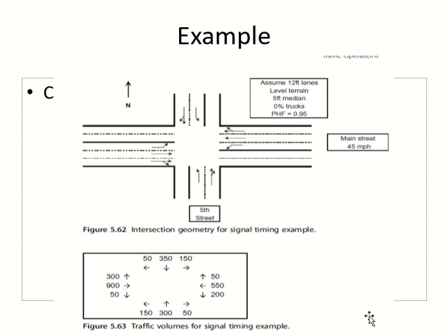Same thing here. This one will have only left turn. This one will have straight. This one will have straight and right both. Now the problem here is what? How many movements for straight here? How many volumes? 1. So some of it will be in this lane and some of it will be in the other lane, right? Because both lanes have this movement.